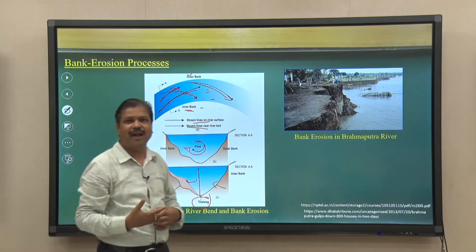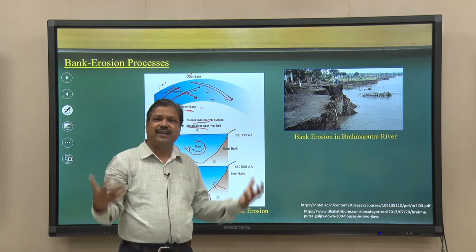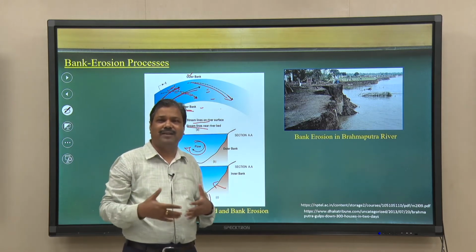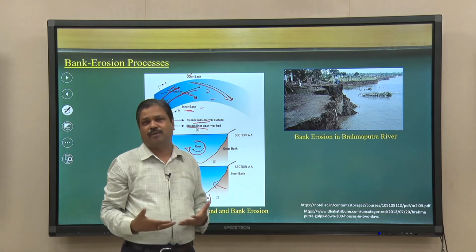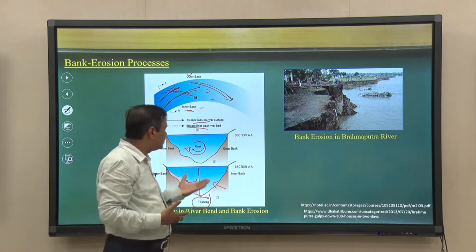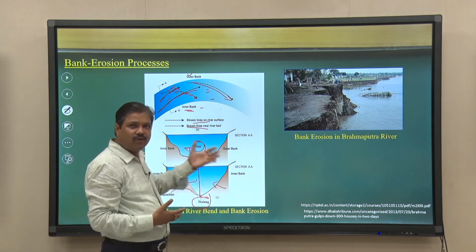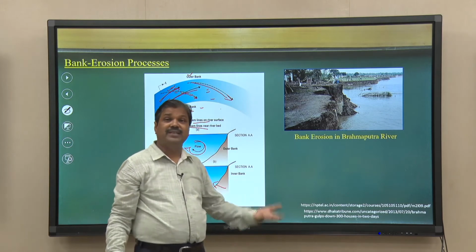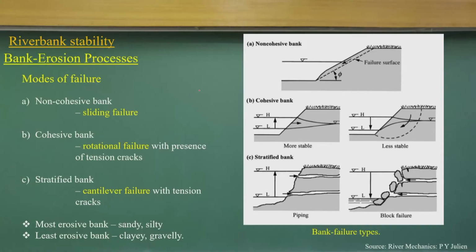So, in the case of a river bend, it matters for us to know what is the strength of the secondary current and what is the geometry of this river bend in terms of radius of curvature, in terms of width of the flow, in terms of the depth of the flow. That matters for us, because that is what initiates the bank erosion process. And erosion and deposition, both processes are initiated because of this secondary current, besides the applied shear stress acting on this bed. No doubt, let me go to the next level, how the bank erosion process happens.